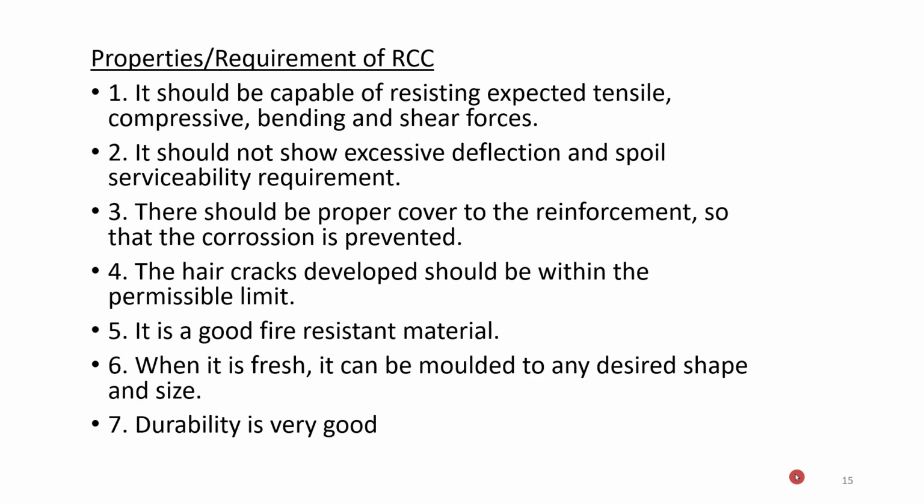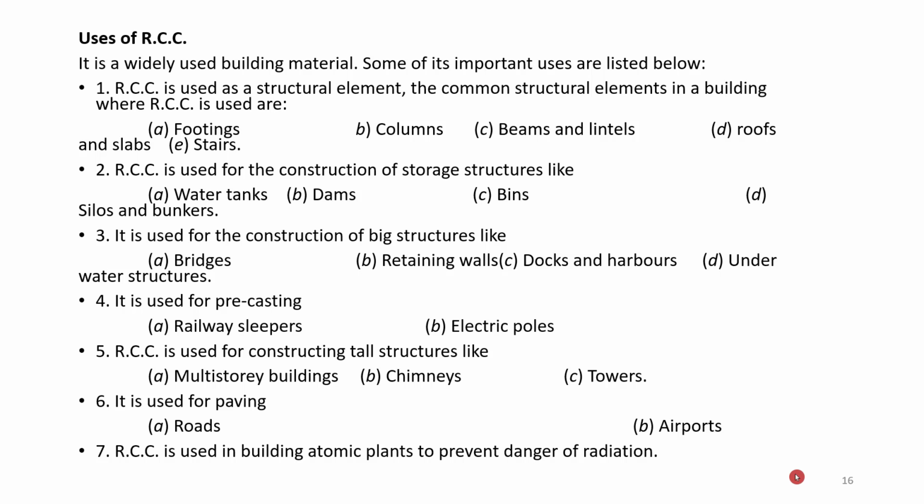It should also be good fire resistant and durable. So we can use RCC for various purposes because we are reinforcing it with steel and now its capacity has increased. You can use it for footings, columns, beams and lintels, for making water tanks, dams, and for big structures like bridges, retaining walls, underwater structures, precasting, paving roads, airports, and so on.